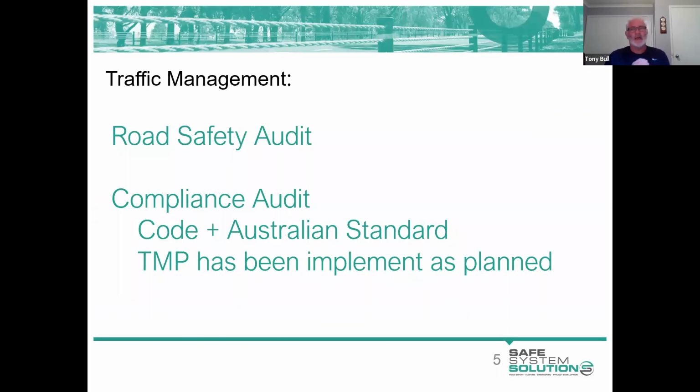Road safety audit in traffic management. We need to separate what's a compliance audit, and that's what our Australian standards, our Austroads guidance material, the Road Management Act and the traffic regulations are all about: compliance. Have we put up our buffer zones? Because there are workers, have we got a worker symbolic? Yes, it should all be part of your audit, but a road safety audit isn't just filling in a sheet with ticks or crosses and the like. This is about what are the safety features that are being compromised at our site.